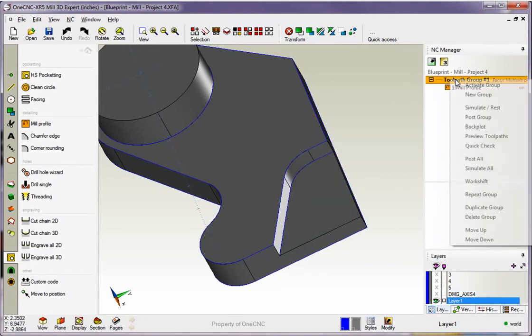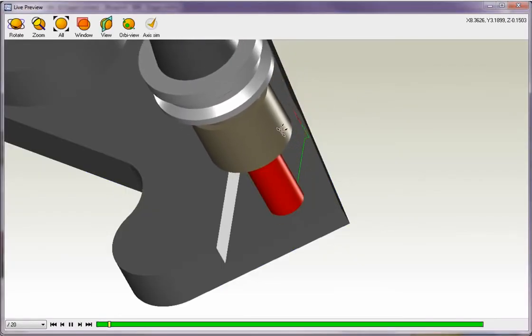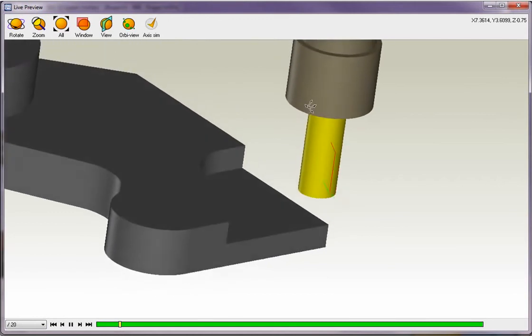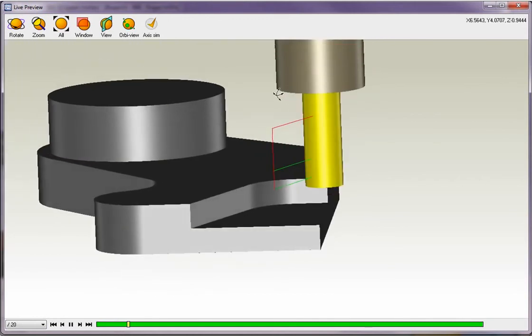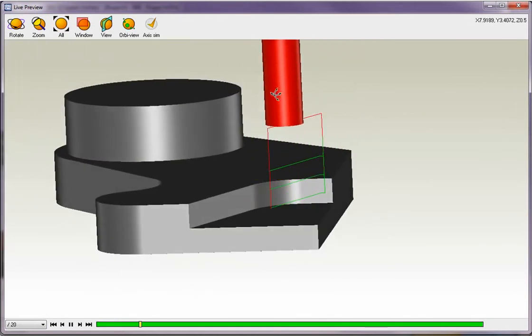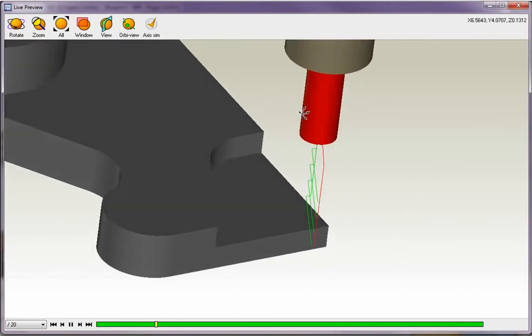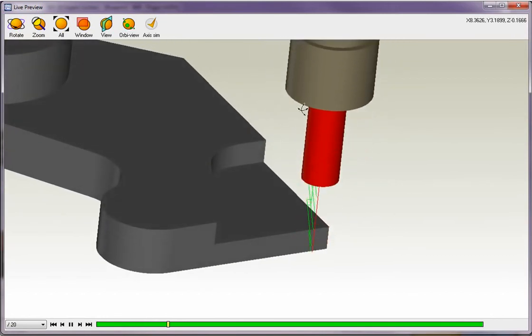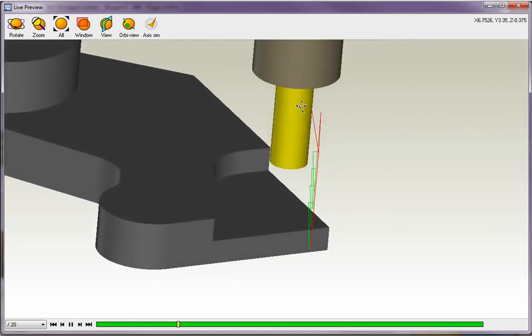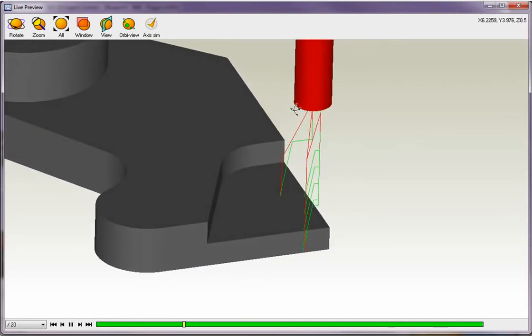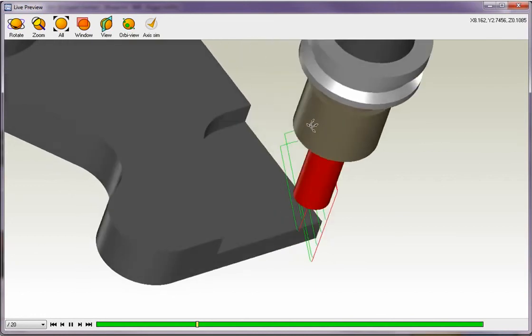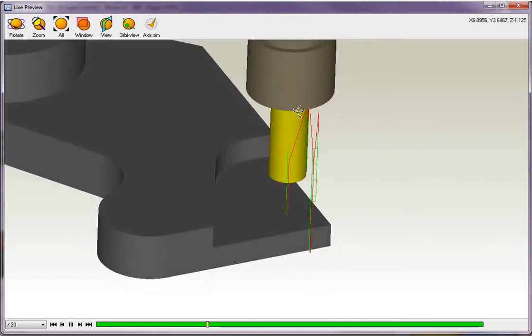Let's preview this really fast. We'll come up here, right click, and we'll select Preview Tool Path. And you can see now that the tool is starting outside. There's my depth of cut, and I think I had 375 thousandths for the depth of cut on that. So after it performs that first concentric pass to the right depth, then it will come over and perform the next concentric pass. And that step over is set to 65% of the tool diameter.